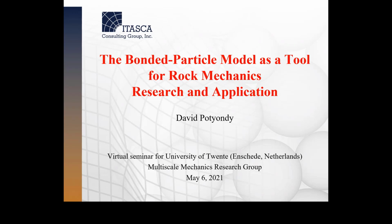Another question is about the bonded particle model. How can you interpret the model compared to other models that use cohesion? Is it the same methodology, or is there a difference between the two methods? So what do you mean by other models using cohesion? Do you mean continuum models, or other distinct element models? Other discrete element models. They use cohesion force to interpret the stiffness between the particles.